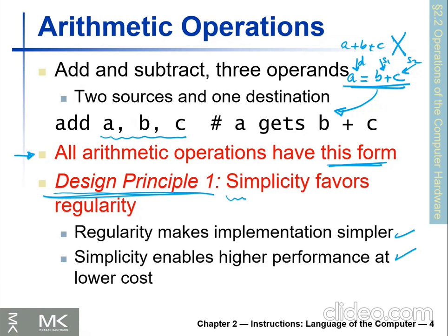Usually simpler circuits can run at very high speed, and complex circuits usually run at a lower maximum speed. For example, if you have a circuit that is 1 square millimeter in area, maybe the maximum frequency it can operate at is 5 gigahertz. If we complicate the design to make it 10 square millimeters, 10 times bigger, maybe the highest frequency is 2 or 3, less than 5.